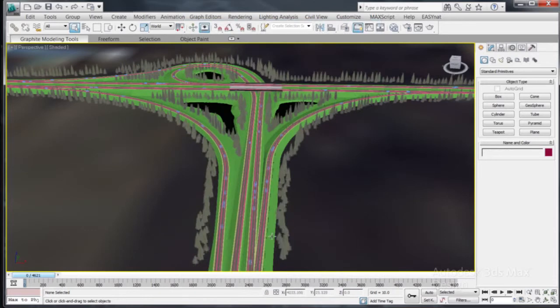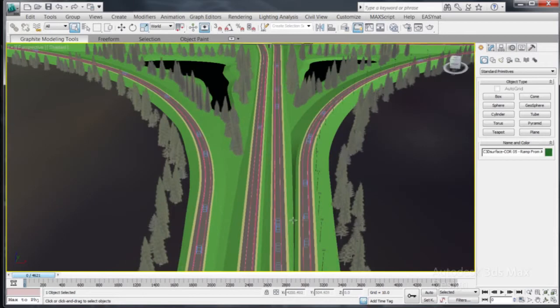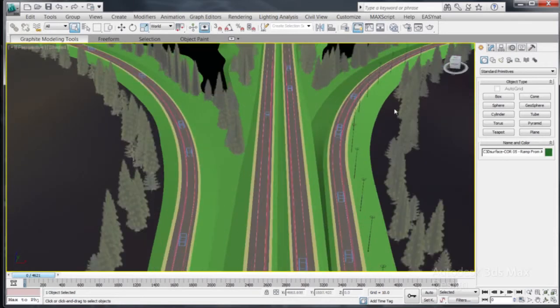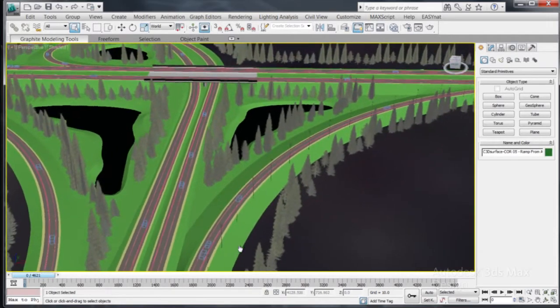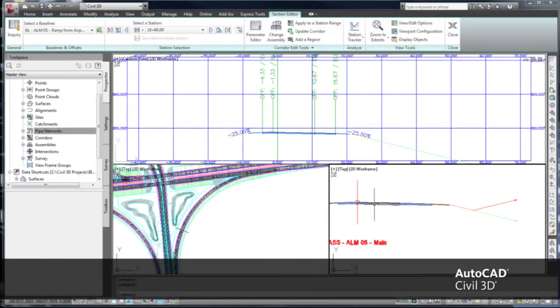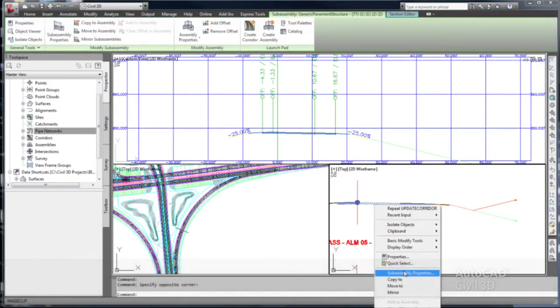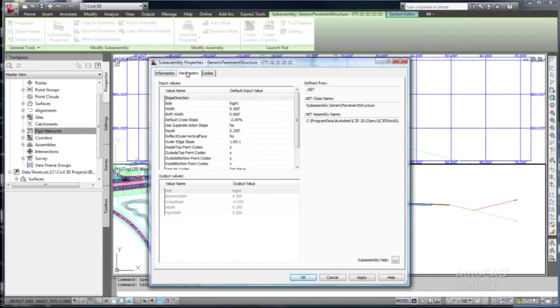In order to effectively utilize visualizations as part of the design process, it is essential that a visualization be able to react to frequent design changes made in Civil 3D. Using the Autodesk workflow, Civil View imported elements retain a permanent reference back to any imported Civil View VSP exporter files from which Civil 3D content has been derived.